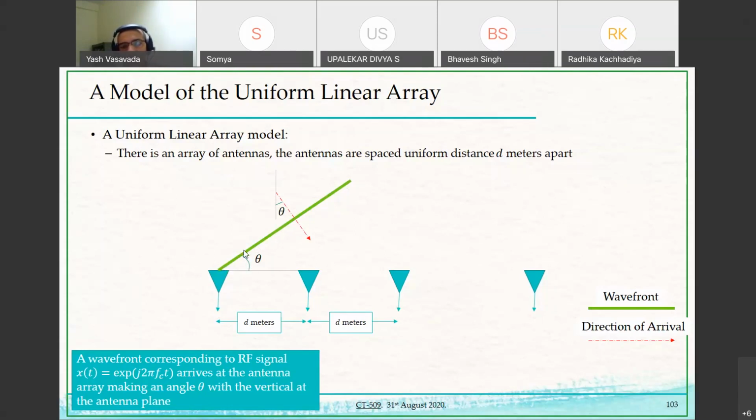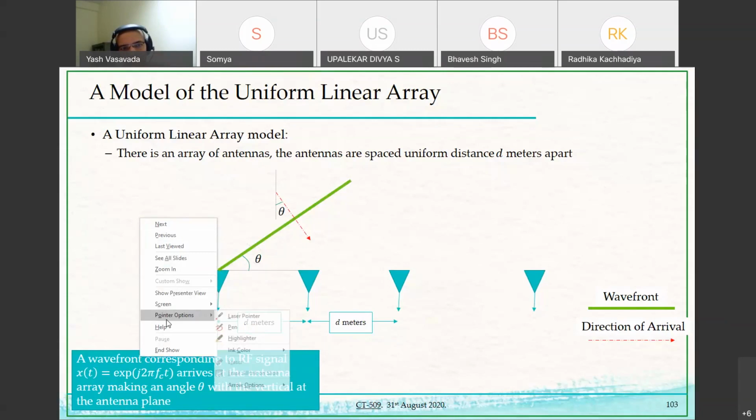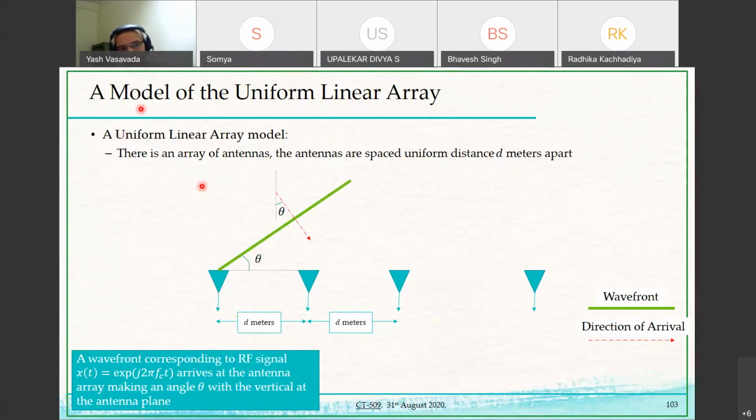at a certain angle theta. And this theta can be drawn in two different ways. Both of these are angle theta. You can easily prove it to yourself. Basically, theta is the angle that this incoming signal makes with respect to the line corresponding to this array of elements. And so we are saying that the signal is arriving from this direction. So it is coming in like this.